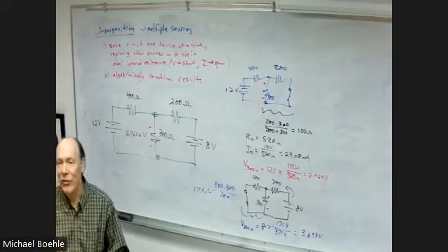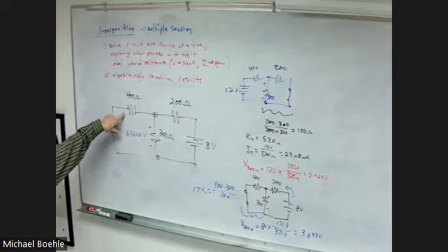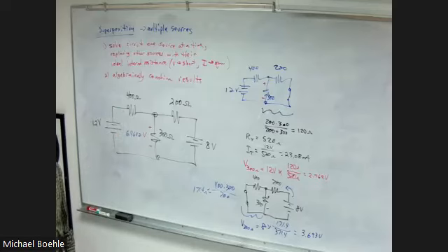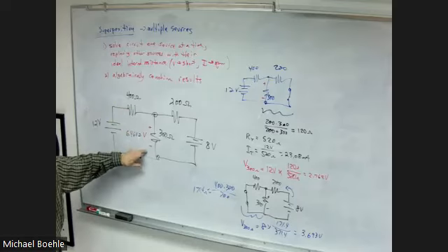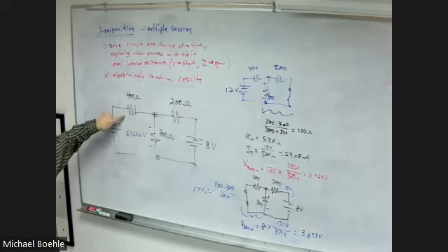Now, the neat thing about this, and I've done this plenty of times in 113, right? I can take that one piece of information. What's the voltage across the 400 ohm resistor? Well, around this loop, plus 12 minus that equals 0. So it's just 12 minus that. So boom, that means here I have 5.54 volts.